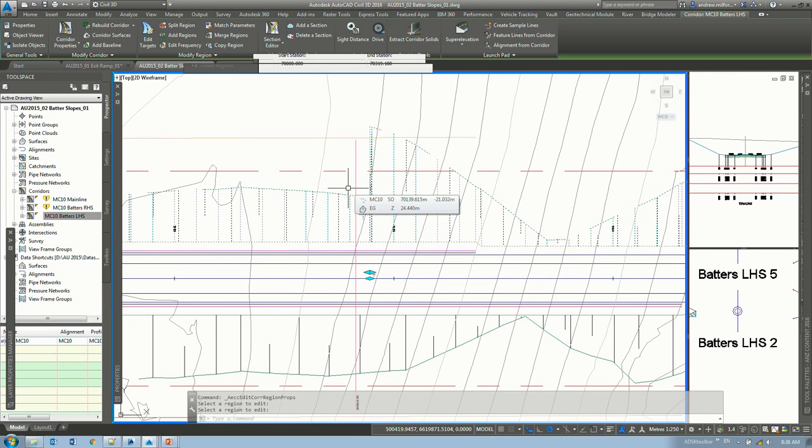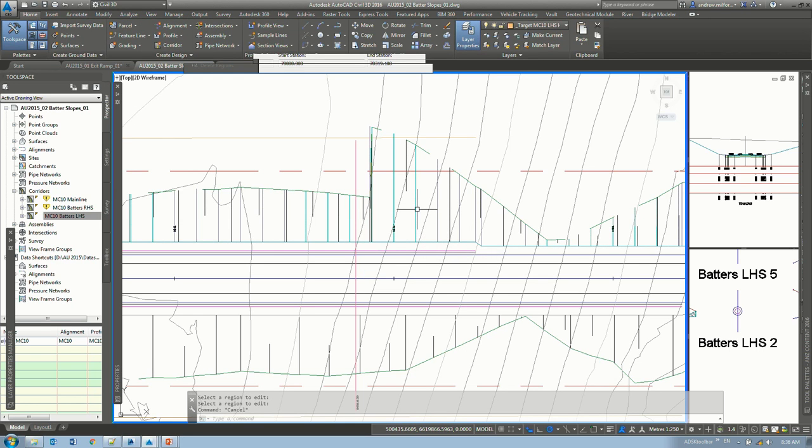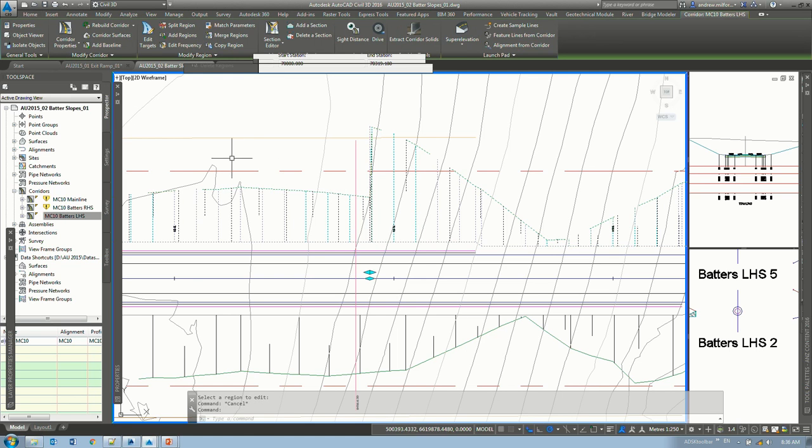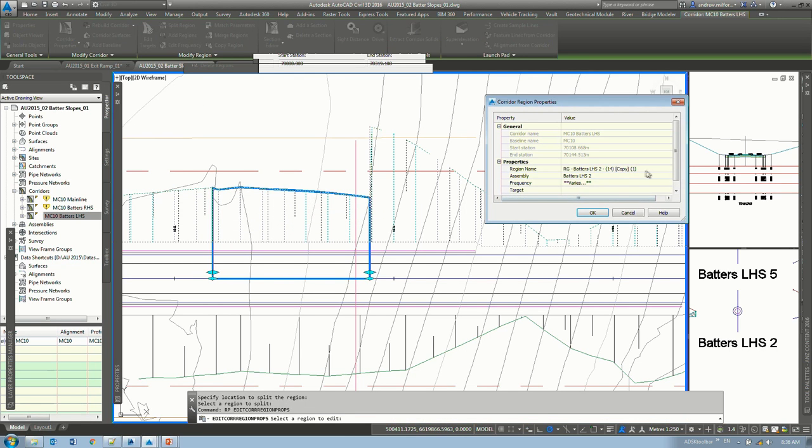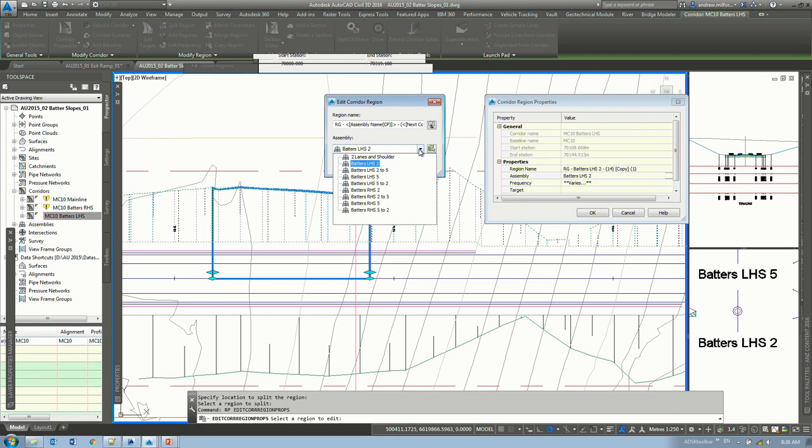There's no way any contractor's going to want to see a model like that. Contractors these days, they want everything down to the nearest cubic metre. So that's why modelling is actually becoming so much more critical, especially in BIM workflows. So what I'm going to do is split this region again. Split it between, say, there, yep. And same approach, region properties. And this one I'm going to go from 2-to-1 to 5-to-1.